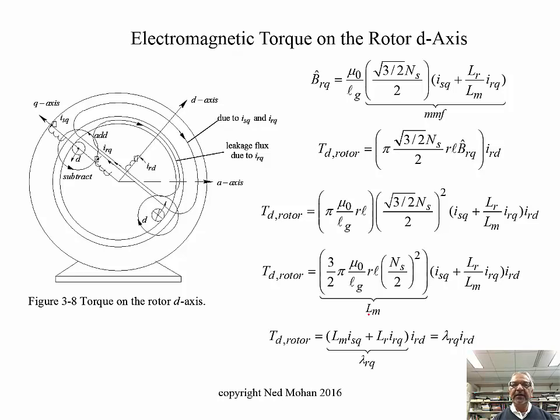And we are in very good shape, because if you want to calculate the torque on the rotor d-axis winding over here, it is represented by just 2 conductors, this one and this one here, concentrated conductors, with the understanding that it's really a winding distributed cosinusoidally in space.